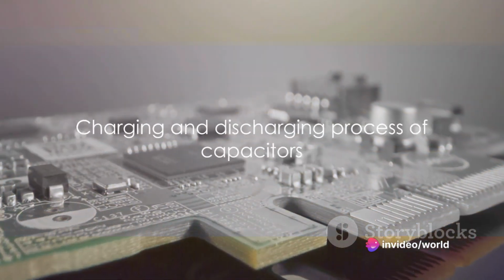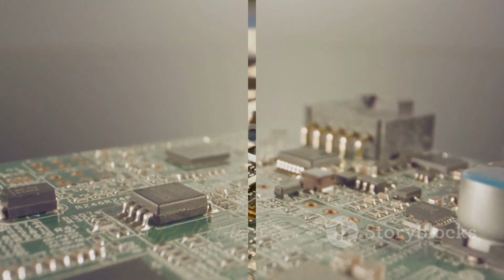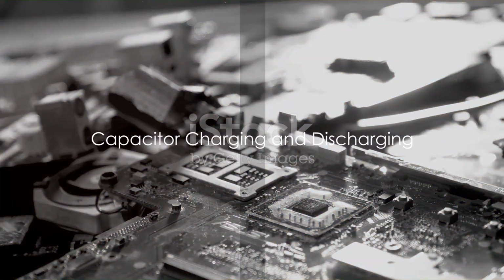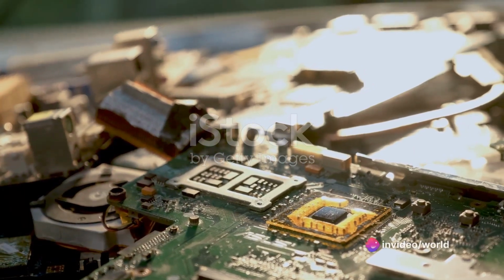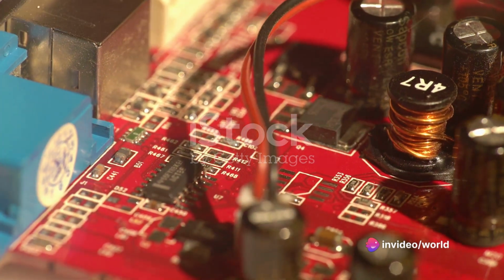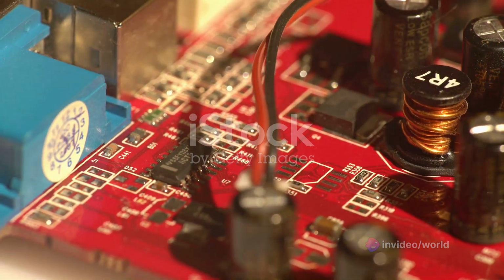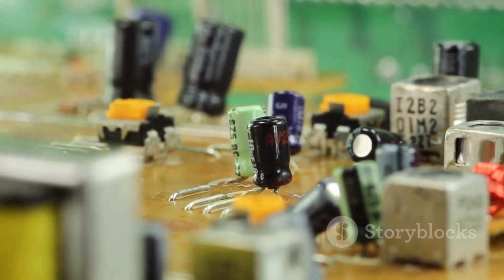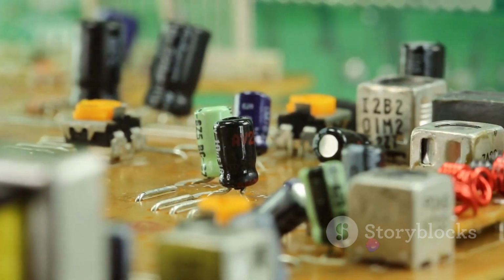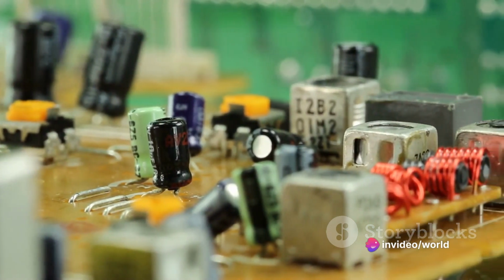Now let's move on to the process that capacitors are most known for, charging and discharging. Capacitors undergo a fascinating process of charging and discharging. Let's dive into this process. In an RC circuit, or a resistor capacitor circuit, the capacitor charges up by accumulating charge from the current flowing through the resistor. The rate at which it charges is determined by the time constant, which is the product of the resistance and capacitance in the circuit.